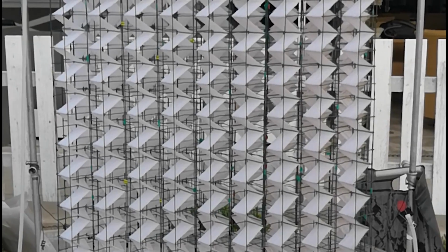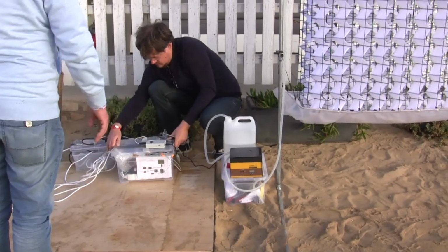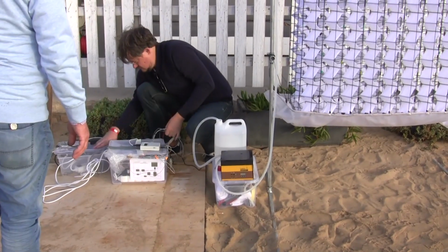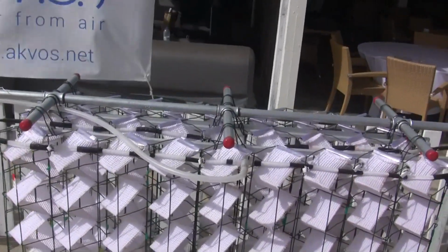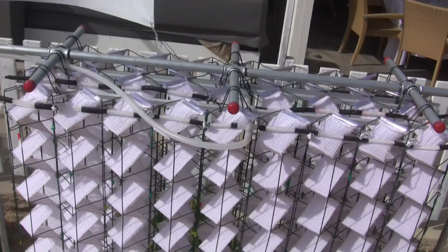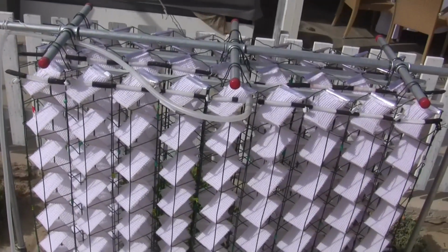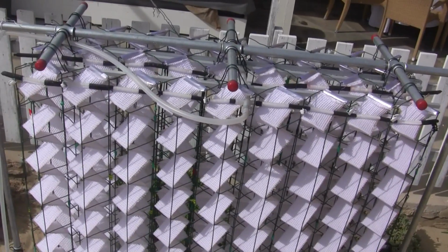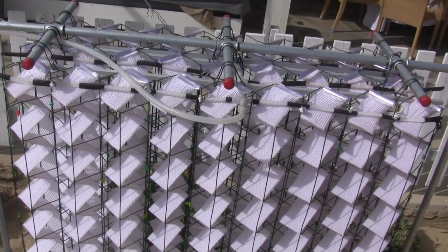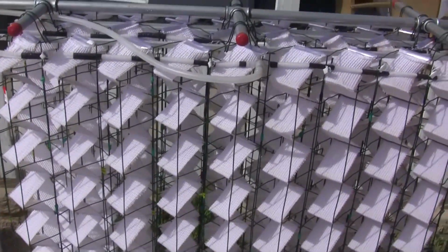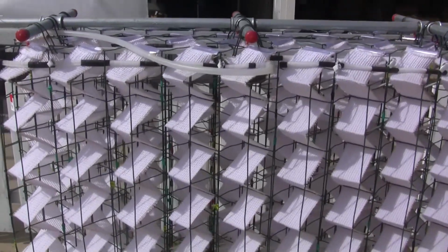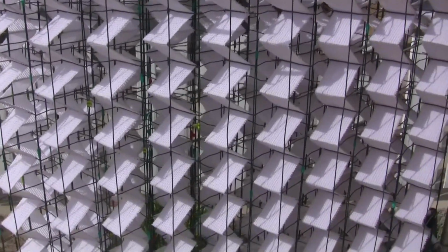For the purpose of this trial, the concentrated glycerol was fed through a peristaltic pump to the upper ends of the cotton textile stripes of the water absorption module. The peristaltic pump allows us to control precisely the flow of the glycerol. Alternatively, the concentrated solution could also flow by gravity through a manually controlled valve, so no energy input would be needed for the absorption process.